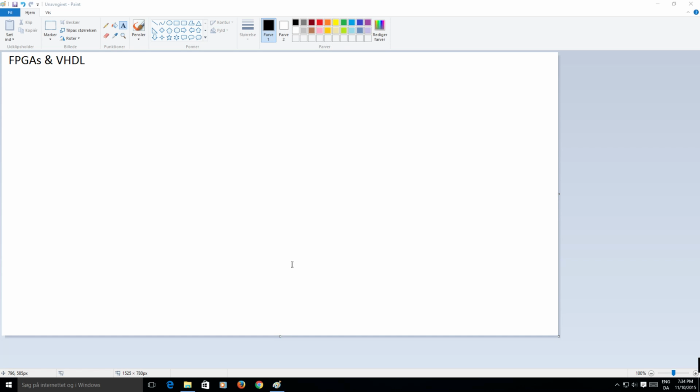So in this video we'll start looking at what FPGAs are, what they can be used for, and how we get them to do what we want. FPGA is an acronym for Field-programmable Gate Array. The FPGA is a whole bunch of logic elements which we can use to do practically everything we want with digital electronics. We cannot do anything analog. That is with the FPGA core itself, because some FPGAs do have built-in analog to digital converters.